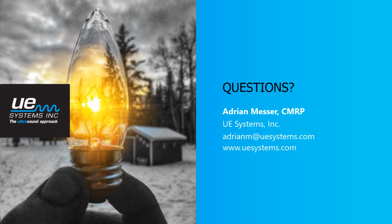Now, I have seen cases where people will create little ports, if you will. They'll just take a drill and drill through the insulation. The thing that I do like about that is the location where we're going to make contact becomes more repeatable. We walk up and we see that little port, and they'll plug that with a little bit of insulation or some kind of covering. But again, we're walking up and we know exactly where we want to make contact. So it makes it more repeatable in that we're testing in the same location every single time.